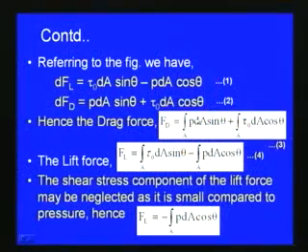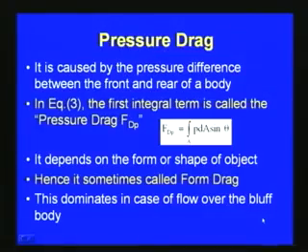With respect to that, we have to consider whether, as in this equation number 3, the major component is the pressure effect or the shear force or shear stress component, and similarly in the case of lift force also we have to consider. As far as drag is concerned, we have already seen the major components are due to the pressure variation, and the shear stress or the viscous effect. So, now accordingly we can classify the drag.